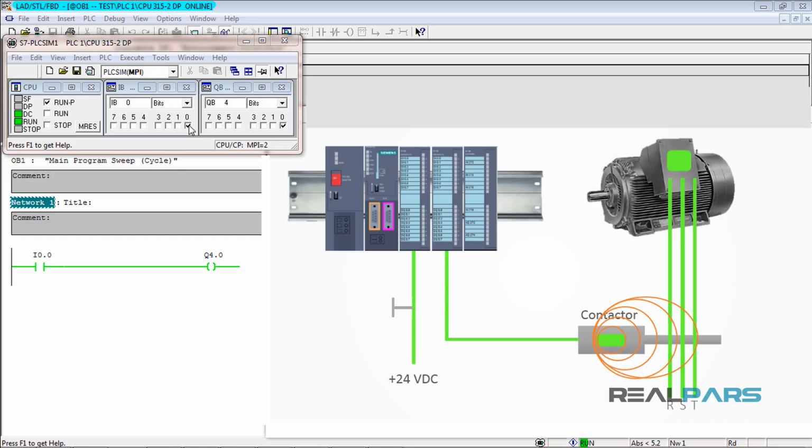So that's our program operating successfully now, but you may have noticed a deficiency in it. When we take our hand off the switch, the input signal to the PLC is disconnected. This means that the motor only ever runs while the button is pressed, which of course is not really very useful. To be useful, we need the motor to continue running after pushing the button once and taking our hand away. In other words, after pushing the input once, the output turns on continuously. What kind of change do you think we should make to our program for this to happen? Go to the next lesson and discover how we can do this.